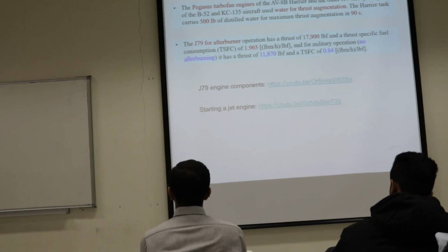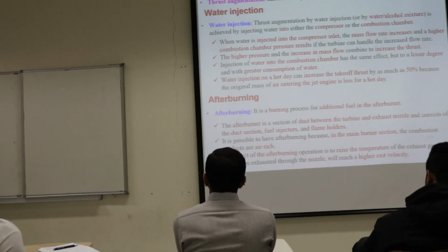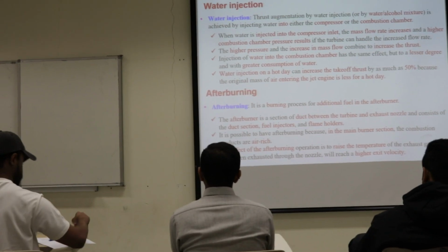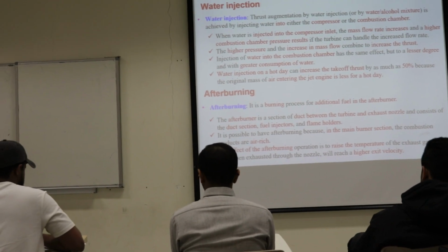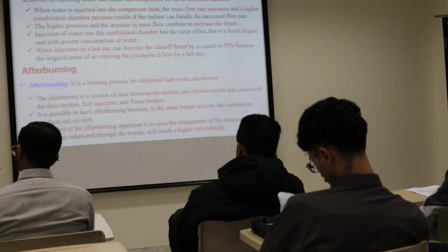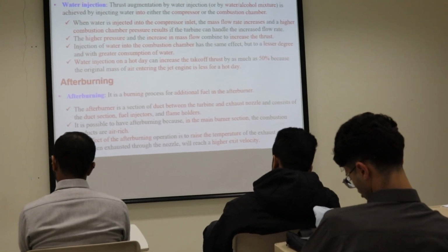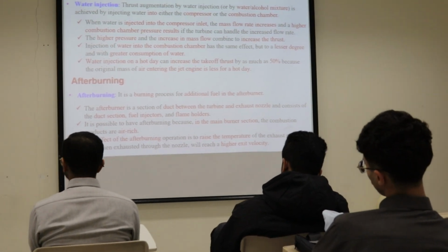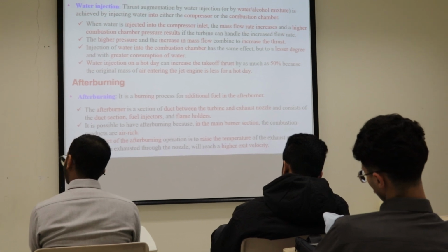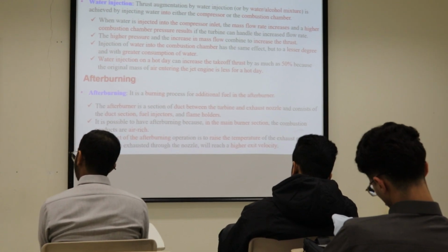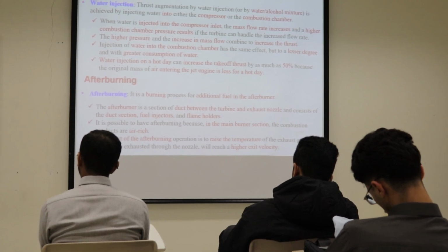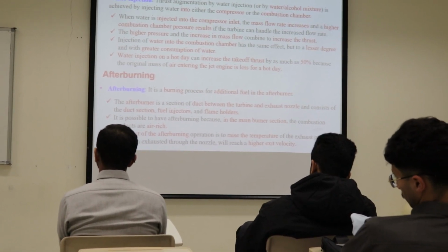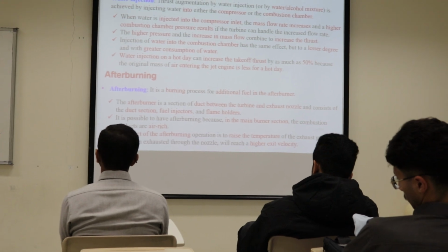Also, Shabab, here in the afterburner, it's a flowing constant area duct, and we have a limiting design parameter for the combustion chamber to have the pressure. What, Shabab? Pressure has to be constant. Okay. So that means if I'm injecting fuel and burning, what I'm doing here is what, Shabab? Raising what? Temperature. Raising the temperature will result in raising what, Shabab? The kinetic energy, and then we can generate more thrust from the propulsion nozzle in this case. So the idea is that I'm not raising the pressure anymore. I'm just raising the temperature to increase the kinetic energy of the gas.